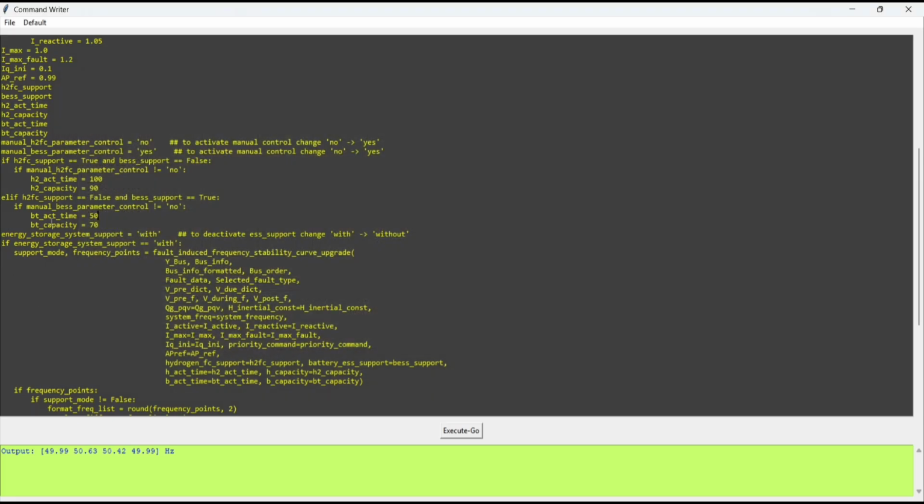Now if I change the actuating time from 50 again to 150 milliseconds, but change the battery capacity from 70% to 20.5%, because, to maintain the good health of the battery energy storage, like lithium ion or any type of battery that works here, the battery is not fully charged or fully discharged in every life cycle. The logic is that the battery energy storage system cannot be discharged below 20% and cannot be charged above 95%.